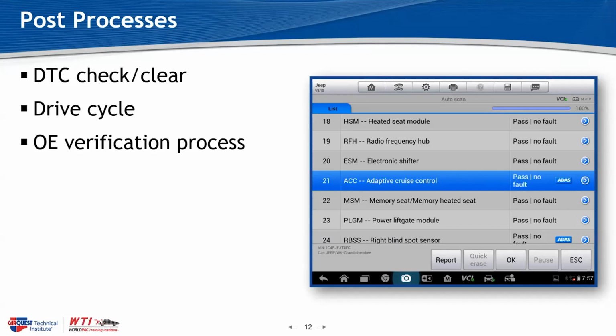I personally try to attempt to use all advanced driver assist systems. I usually have to go in and turn those systems on or off, and I make notes of how the customer had the system set up beforehand. The most recent one I had that was way off was a Ford, and the customer had almost everything turned off. So I went through and turned all of it on, made sure it all worked and functioned to what I thought was normal according to service information and what I could find under description and operation,